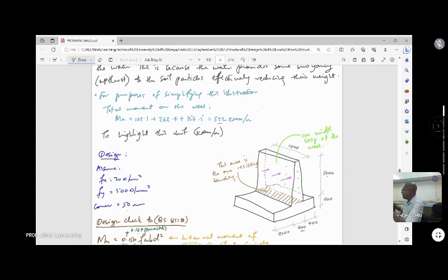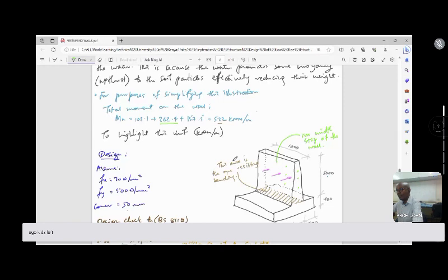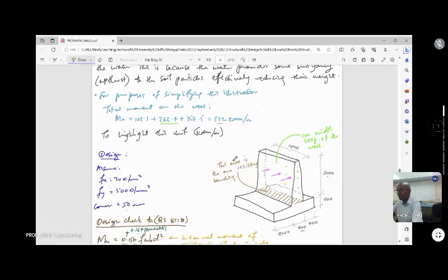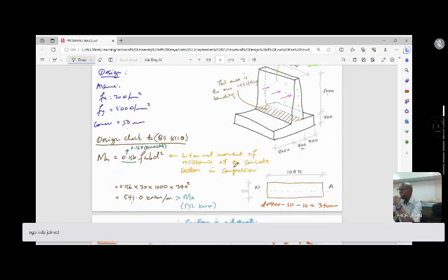And if you look at those walls, now that this road has been in service for a while, you'll see that actually water does escape through those holes. So you'll see the mark of water that flows down from those walls, and effectively that removes completely this component of the bending moment. And of course the pressure removes and the bending moment also removes.